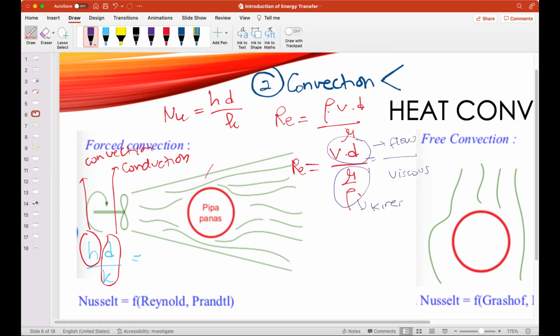So in Reynolds, if you have a high Reynolds number, or turbulent flow, your momentum transfer is dominated by the velocity of the flow. But if you have a low Reynolds number, like less than 2000, or maybe just 1, 2 or 3, where it is a very laminar flow, your momentum transport is dominated by laminar flow.